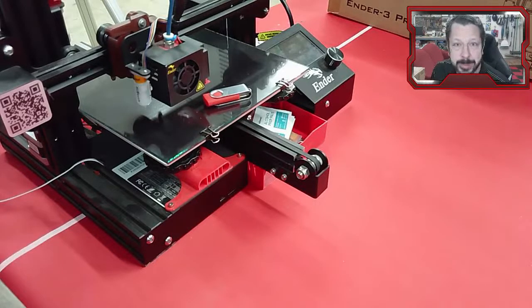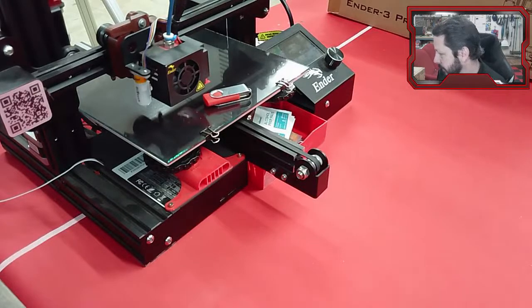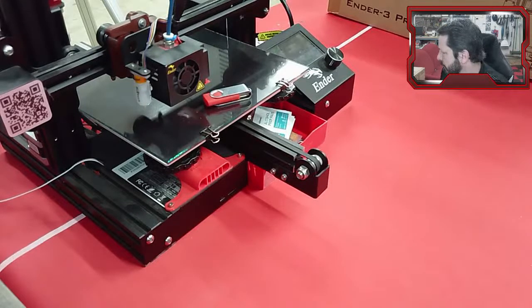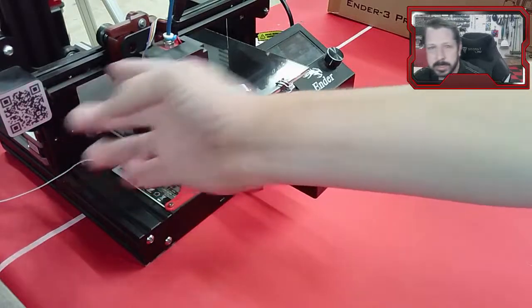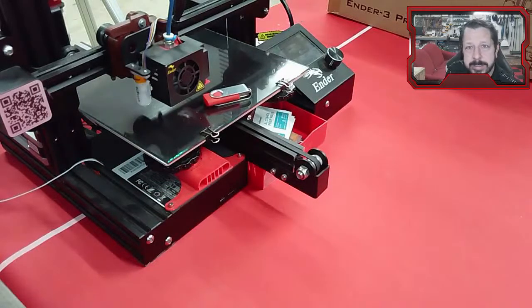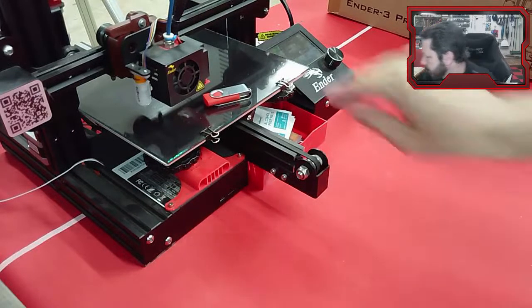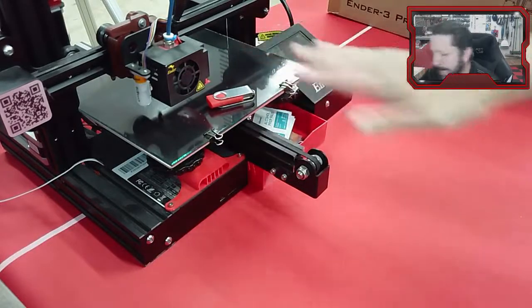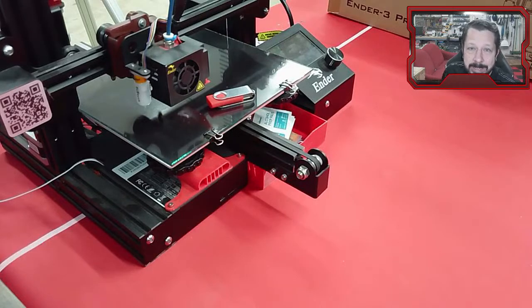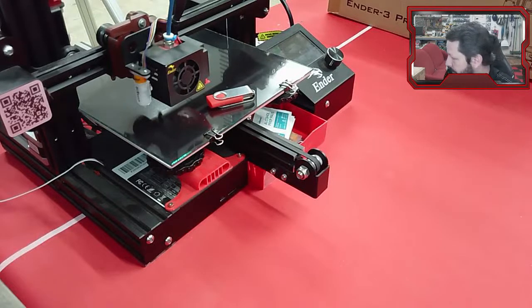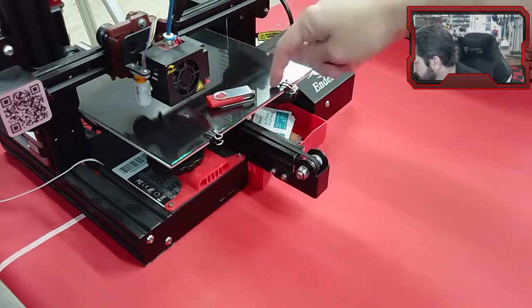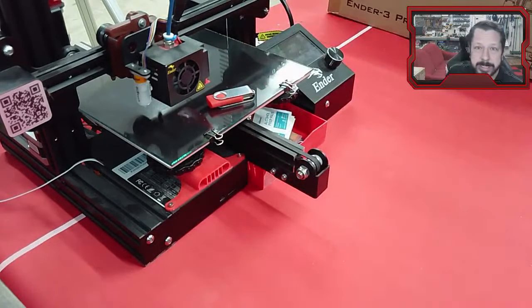In fact, it has no feedback. On the stock Ender 3 printer, there's no feedback at all. So it has to assume everything. So there's limit switches normally, little clicky switches that tell it where the end is and where the top and bottom and the back of the bed and things like that. But the bed itself may not be level. It may not be flat. It might be all warped, with hills and valleys and all that kind of stuff. So this little probe can go in and tap on it and kind of map out the bed.